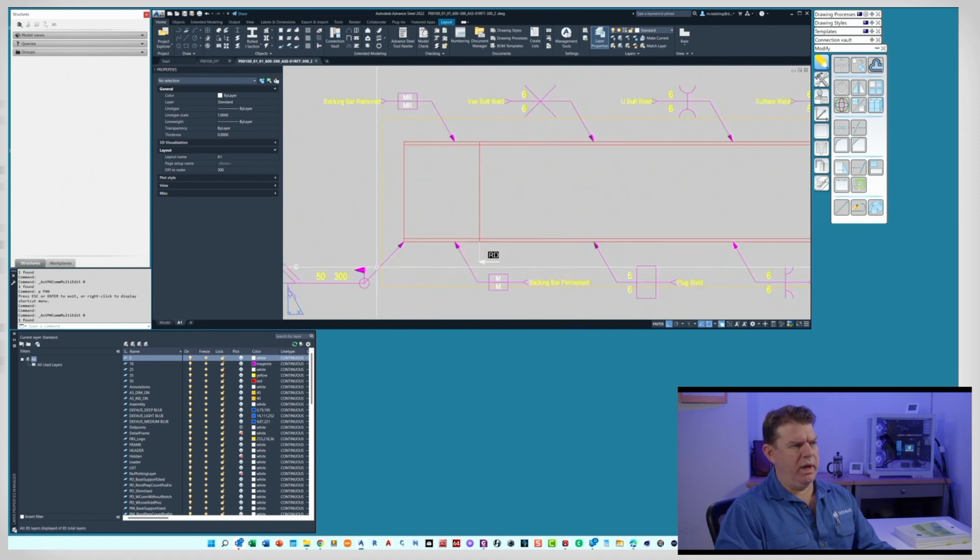So what we have decided to do in our business is this. Traditionally people would put a note on their drawings to say that a 6mm fillet weld, or if it's a fillet weld and it's not noted, it'll be a 6mm weld. The reason behind that theory is it's come from how we used to do things back when we were on a drawing board.